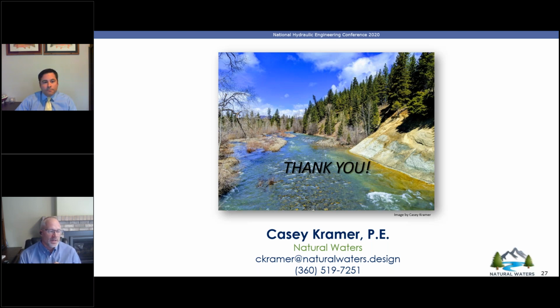There are best practices. I do think it's going to be challenging in general to do a no rise within a 2D model, and I think there are some best practices to be learned, like using the same mesh for the existing conditions and proposed conditions, even though the terrain may be different. Those are the kinds of best practices we can learn and help promote to better enable a no rise. So certainly stay tuned, stay in touch with us on the webinars. As we learn information and best practices, we'll certainly help promote them.